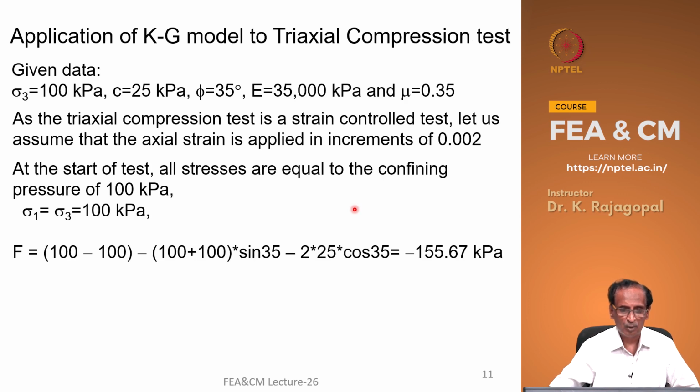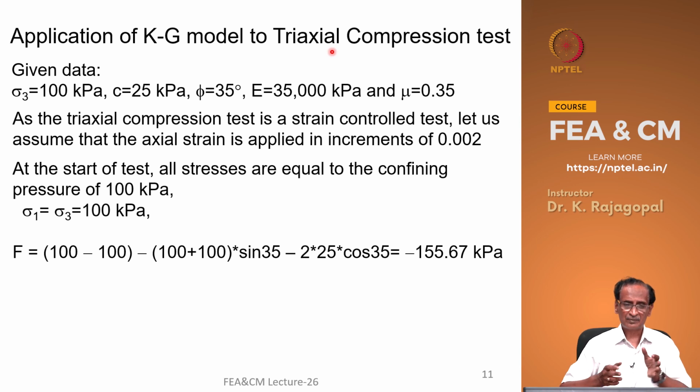Let's apply this model, the KG model or the bilinear elastic model, to a triaxial compression test. This demonstration is suitable for hand calculations, so that you can understand the procedure, but the same thing we can apply in any finite element program, where there are several calculations that we cannot imagine doing by hand.